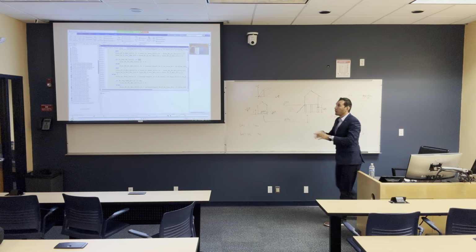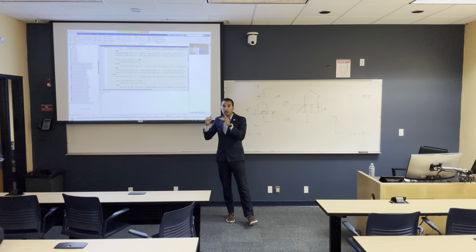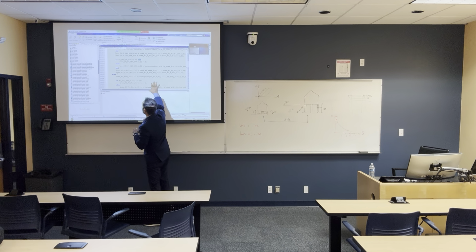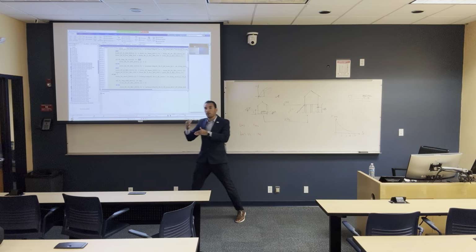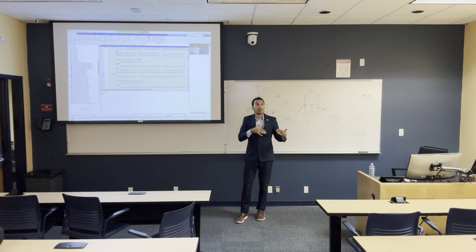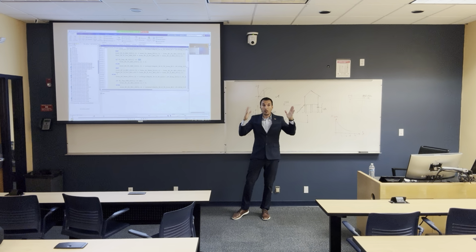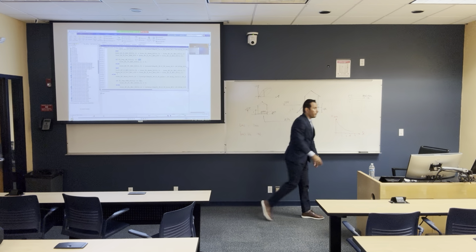Why do I write the same code? Because all we have done is just for archetype 1 and 3, and we are interpolating at a flood depth measured from the ground elevation. So I'm starting the else, copying the same code and changing the flood depth from the ground elevation to FFE, all right? Because we have archetype 1 and 3 with flood depths measured from the ground elevation. You guys remember? Archetypes 1 and 3 are special, and they have a crawl space foundation, so we need to start the flood depths measured from the ground elevation.